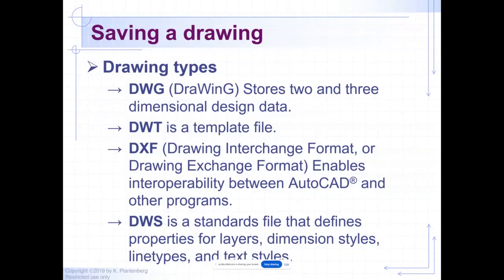Don't get that confused. I get people turning in their Chapter 4 stuff as template files instead of drawing files. You only use the template to start with. You don't actually open it. It opens up a copy of it, okay? So you don't actually go and open the template and then save it as something else, because that'll get you into all kinds of fun and trouble.